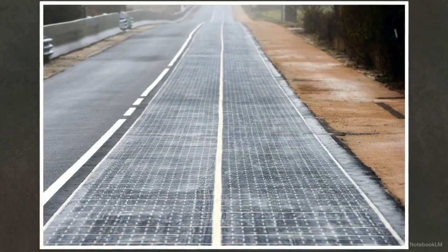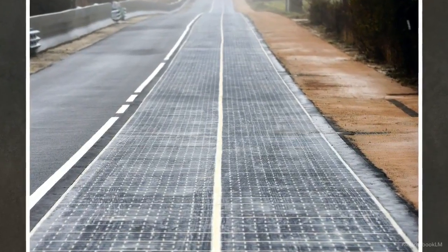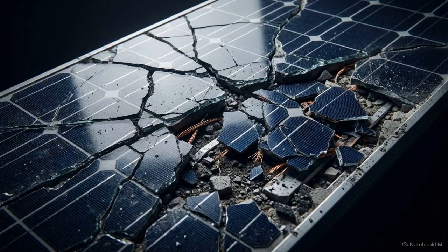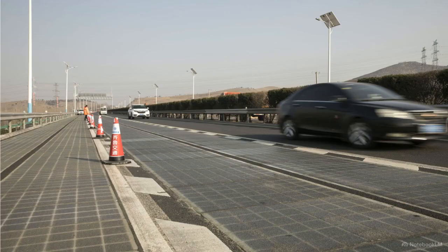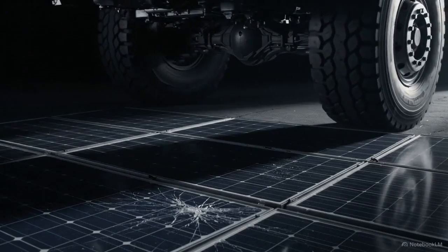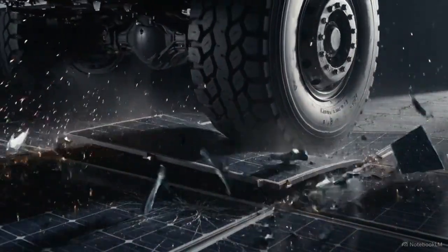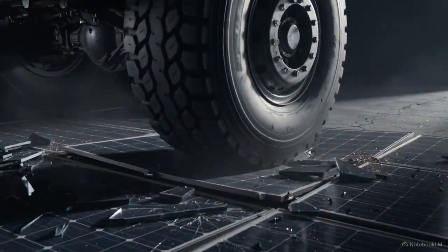In 2016, engineers installed a kilometer-long solar pavement on a public road in Normandy, France. Within 3 years, sustained vehicular loads caused severe cracking and delamination, halving the power output annually until the project was ultimately abandoned. A year later, a similar modular solar highway was constructed on the Jinan Expressway in China. Under the complex dynamic loading of heavy highway traffic, the structure suffered widespread mechanical failure in just 8 months.